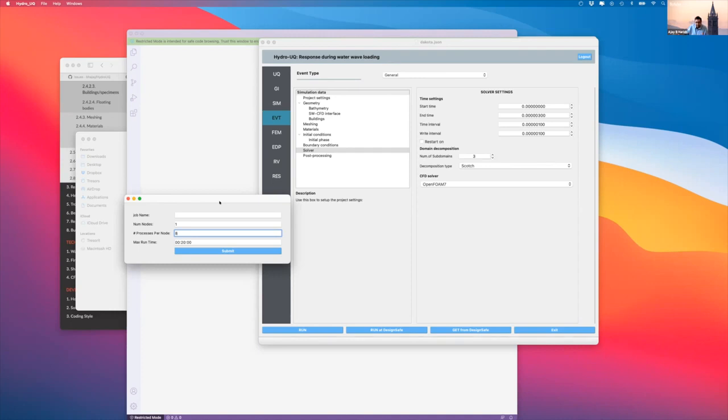So both of these are kind of equivalent there because each of these is basically, for TAC, a 20 MPI task, nothing more than that. So if you can use one node and if you can get up to 62 processors, then I would go with one node and 62 processors rather than spreading them across the nodes. That would probably be the recommendation. Also, it's much easier to find things if you're looking on one node, and your job might start much faster than if you're trying to get processors on multiple nodes.